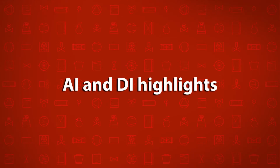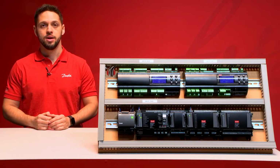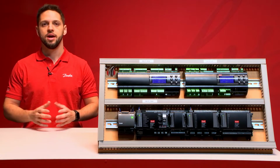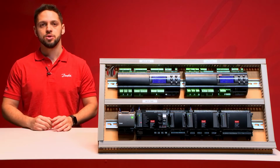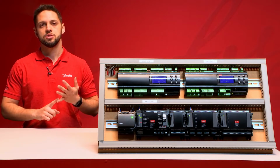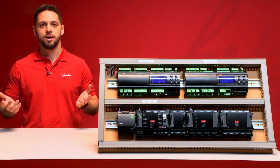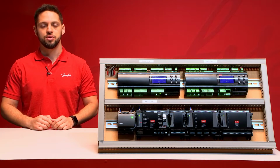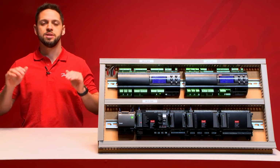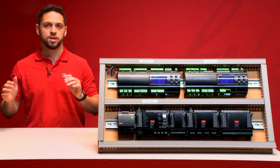And now, let's focus on the inputs of the new controller. As I mentioned before, we have enhanced the inputs of this new controller. So now you can use PT1000 temperature sensors, or you can use NTC temperature sensors in any of the analog inputs. And also there's a very interesting new feature for this new controller. Now there is noise filtering. So it means that you can have pressure and temperature readings much more stable than before.